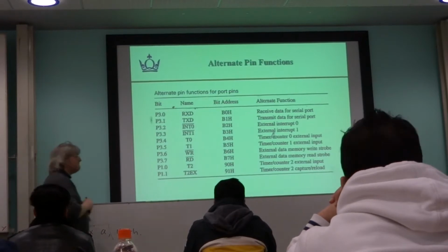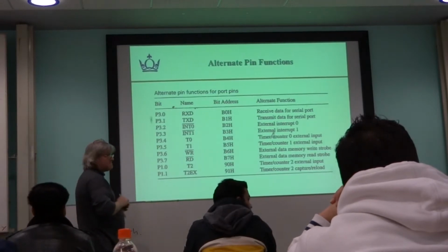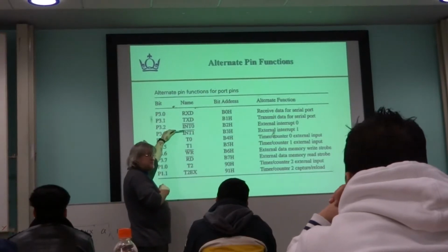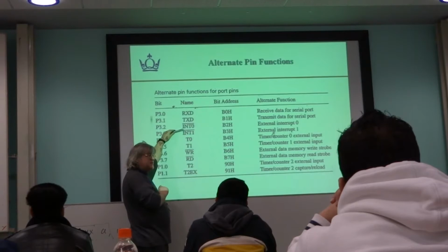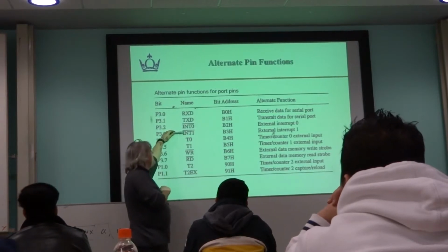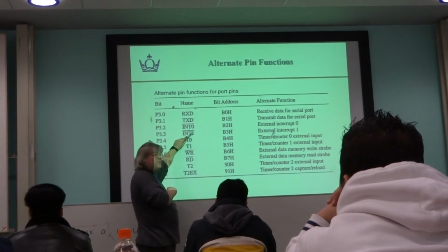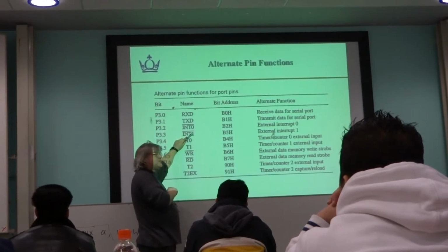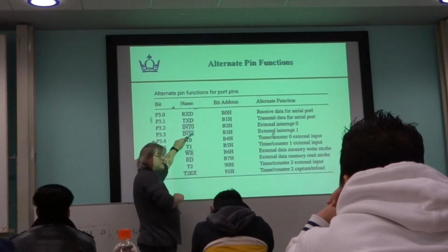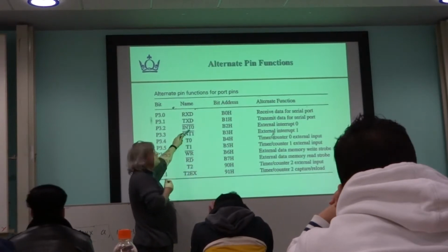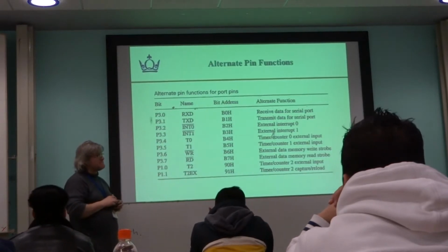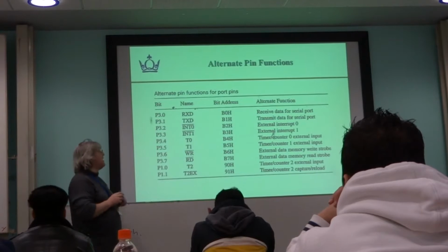Yeah? Can they count as 4 interrupts? Each one of these has its own special interrupt. It goes to a special place for each one of those. You can wire up multiple sources of an interrupt to it. So you might have 4 things that are all wired up to that one pin. But then the question is, well, which of the 4 caused the interrupt? You would then have to write some software to go and interrogate to find out which one caused the interrupt. I mean, if you write like 0, 1, and then like 1, 1, or 0, 0, can they represent it?